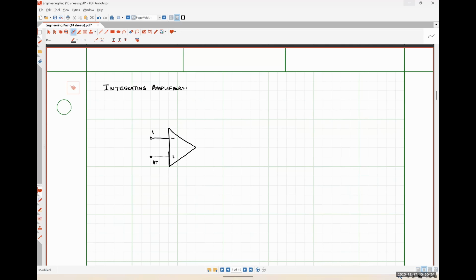All right. So let's see, this will be V plus, V minus, V out. VCC plus, VCC minus. So I think I mentioned it a moment ago, but in this case, our capacitor is going to be in our feedback position. So I'm going to call this C sub F. We're going to have a resistor here. So this will be, let's just call it R. Our input signal is going to be applied over here on the left-hand side of that resistor R. And like we had earlier, our non-inverting input pin is going to be connected to ground.